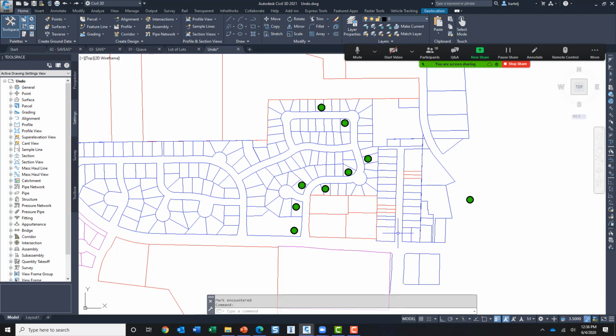All right. Now, important to remember, markers are not drawing persistent, so that means when I get out of the drawing, all the markers are flushed. I can't come back tomorrow and roll back to a different point in time. It's only during the valid session that I'm currently in. So very, very powerful tool.